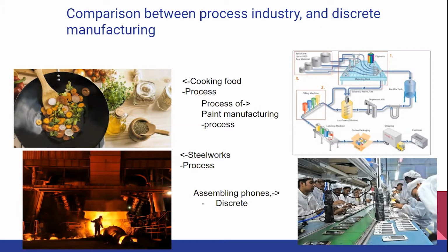In industry, there are different process variables, as I discussed previously, where they control temperature, velocity, and things of that nature that really affect the making of the product. For example, in paint making, you have raw materials such as solvents, oils, resins, and tints. Those raw materials go into the metering deck and get dispersed. There are 4 different colors here, so there are 4 different tubes, holding the different colored pigments that you want to use in the paint.